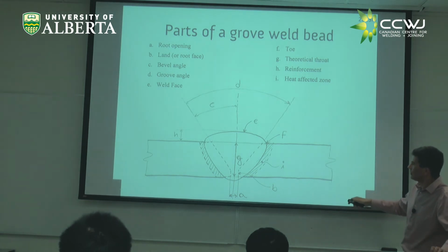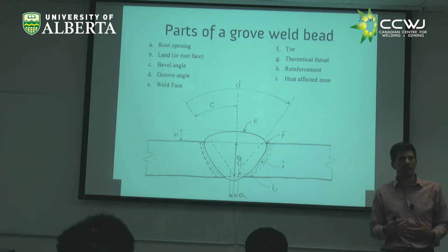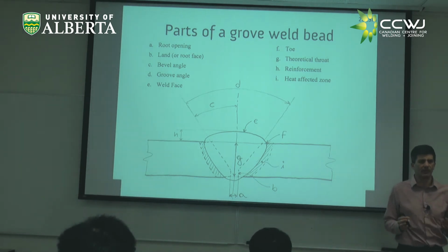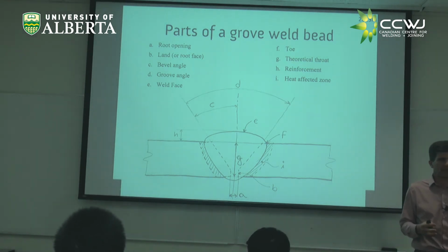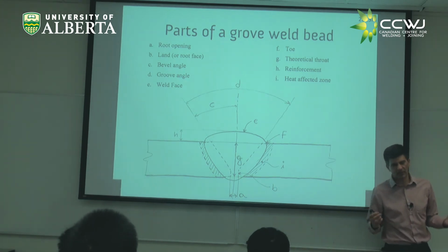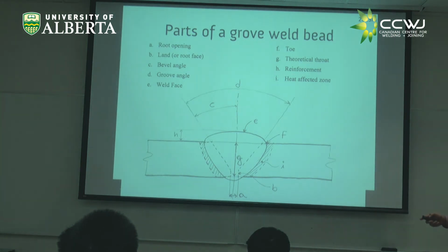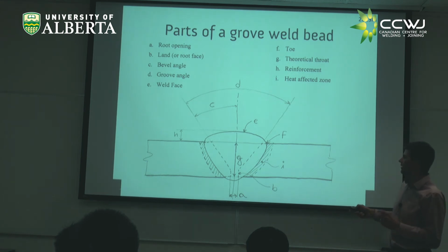And then something which we are also going to discuss quite a bit in this class. You see this part that surrounds the weld? If you do the metallography, you're going to see that the metal there is all funny. That's called the heat-affected zone, right? A heat-affected zone means the heat somehow affected it. And we can do lots of calculations about that. Extremely important. Most welding problems are in the heat-affected zone.